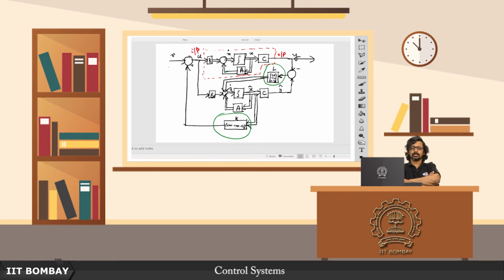And then we went into this state space description of systems. So from an ODE or a transfer function, we saw how we can get to a state space form, that is x dot is equal to Ax plus Bu, y is equal to Cx plus Du, right. And then we saw these interesting different realizations. There are many other realizations that are of interest to us, but we saw chiefly three types of realizations.